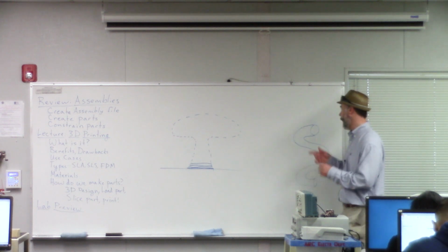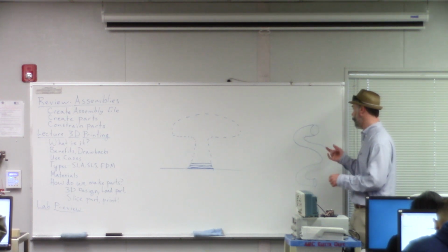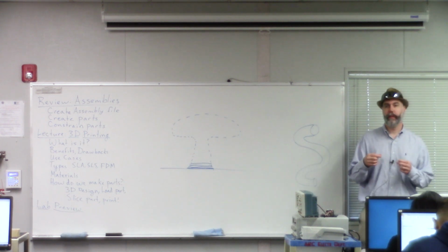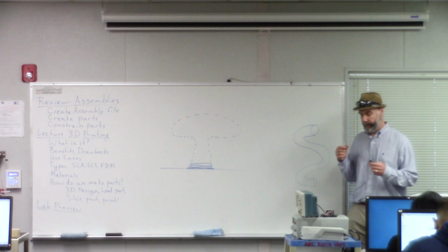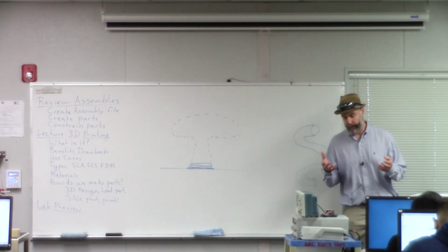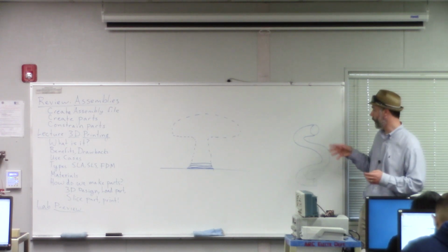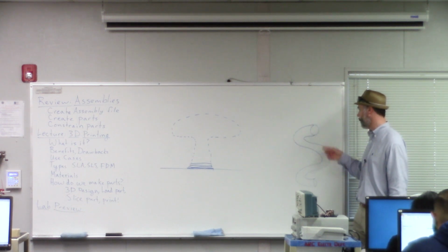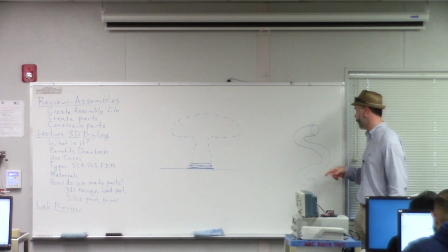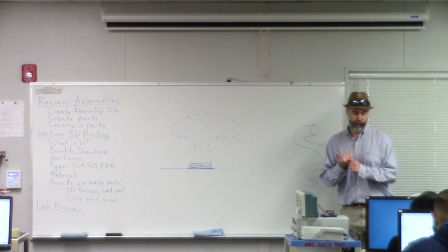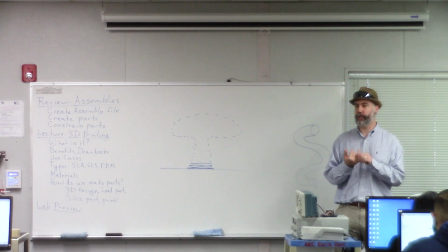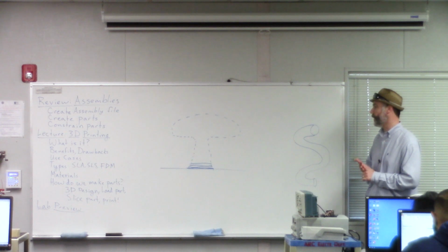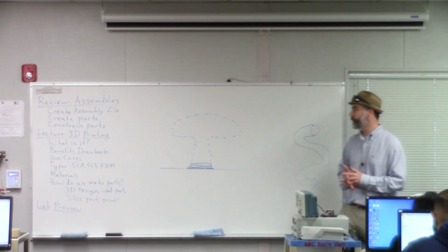So those are the main benefits to 3D printing. You can have these really wild shapes that you can't really make with molding, or even with CNC machines. There are milling machines and things like that that can cut parts, but they also can't cut these internal shapes, and they have a harder time with weird curves like that. So 3D printing can make these really wild shapes, and it can also have a very short cycle time. Those are the main benefits to 3D printing.